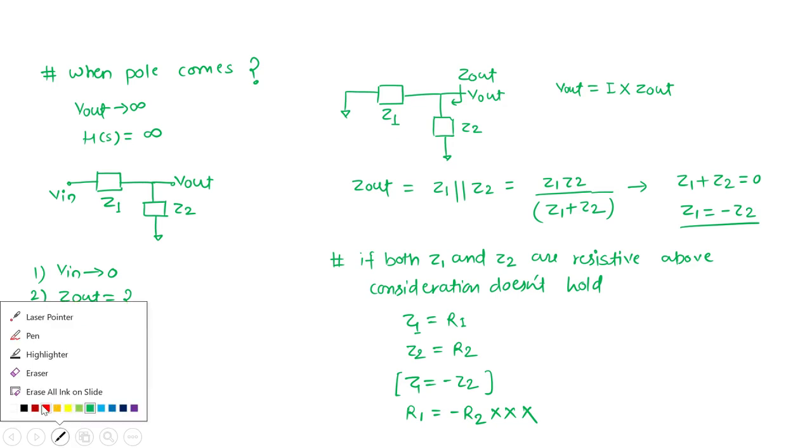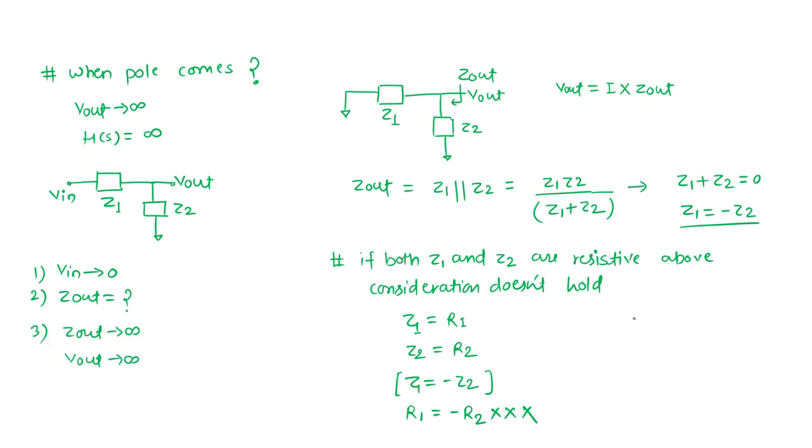My dependent current source, my GM cell, was saying this Z1 was nothing but R out, the impedance of my current source, which is V in times GM. And what was my Z2? Z2 was my capacitor. Then we could do this. What was my Z out here? Where V in is zero, I can make it open, which means this current source I can make open.